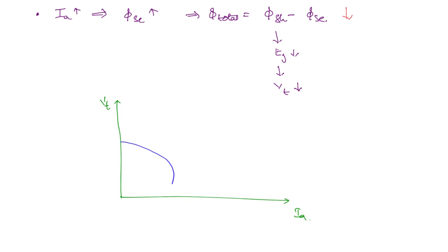In contrast, if you compare with the shunt generator, it is going to be something like this. Okay, so this is differential compound generator. And once again, if you want to get the internal characteristic, this is the external characteristic, then you simply add the voltage drop across the armature and series winding, then you will get the internal characteristic.